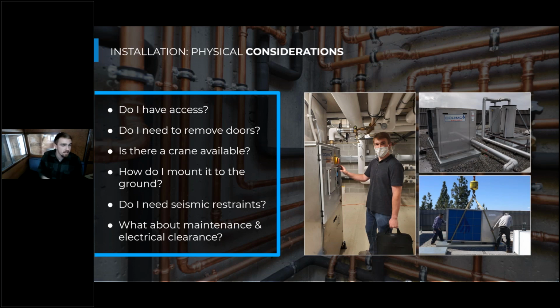And another thing to think about here is the seismic restraint of the equipment. A lot of heat pump water heaters are pretty low to the ground, so they might not need physical seismic restraints aside from the mounting points that they're bolted down from. But there's often vertical storage tanks that you need to consider the seismic restraint for as well, and kind of fit that into any maintenance clearances that you're planning for this equipment.